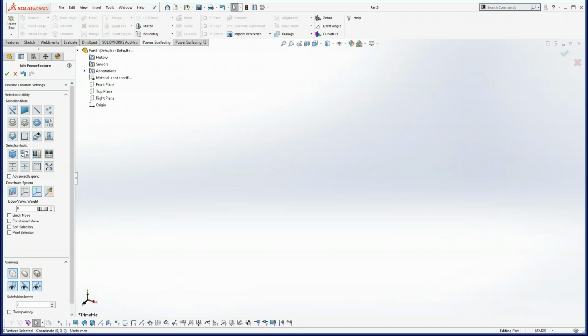Can you use sketch curves as surface control curves? Yes, you can constrain to sketches, actually in multiple directions too. That's another feature that's new in the 5.0 version. One of the things that we didn't mention, mainly because it's not something you can see, is that the files are now a lot lighter weight and the conversions are a lot faster than the earlier versions. And there are probably other under the hood things that I don't even know about, but there were a lot of changes in this version. That's a good point, Sue.